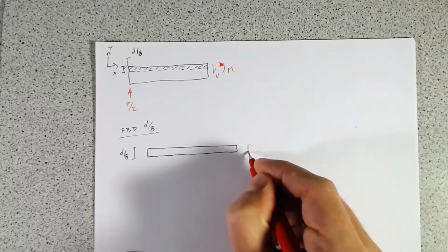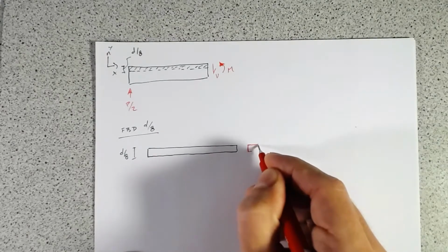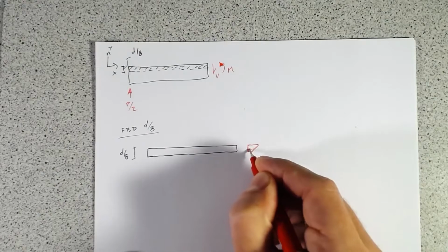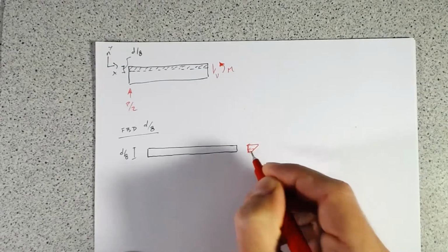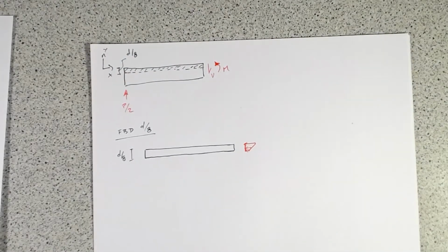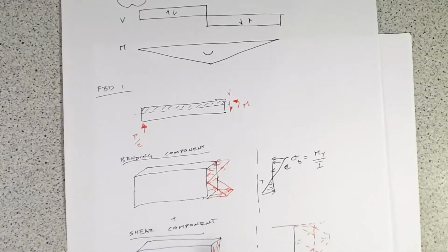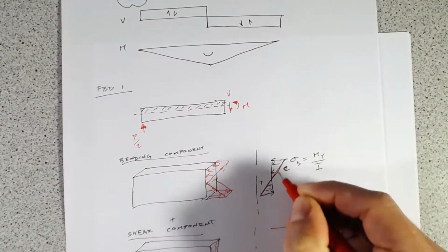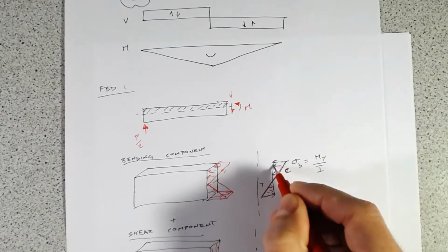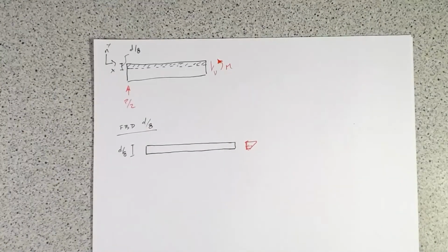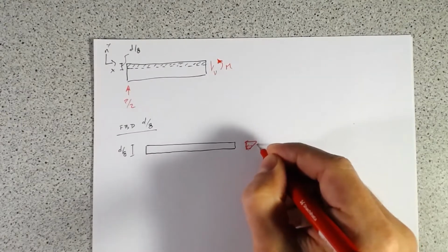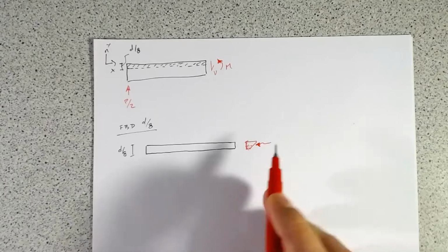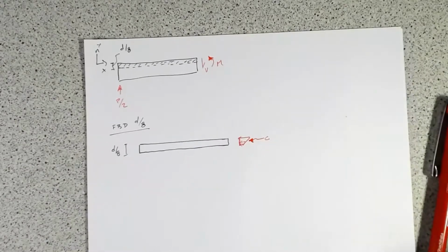So we will have a bending stress distribution like that. So it's kind of the top of the triangle here, right? If our total profile is a linear distribution of bending stress, we're looking at the top 1/8 of it there. And so there will be some resultant compression force, C, acting here.